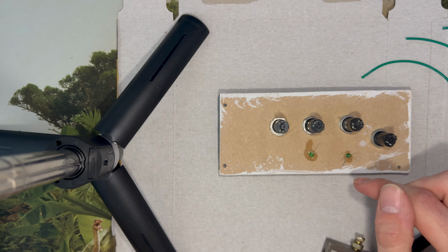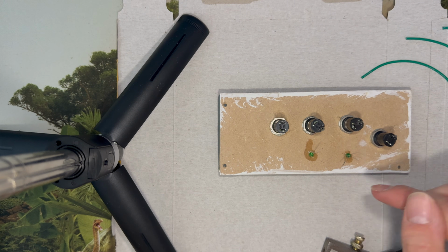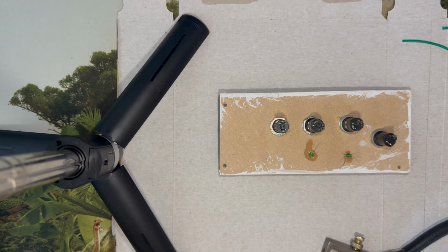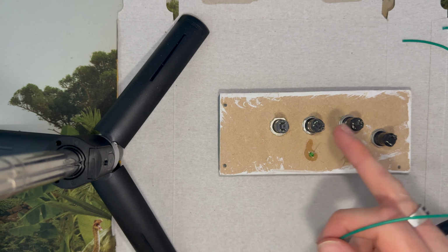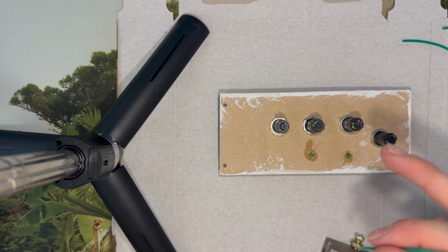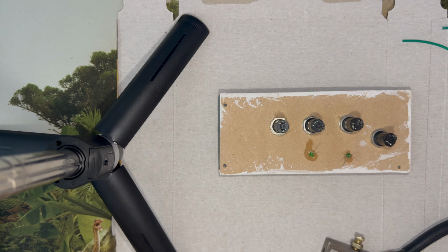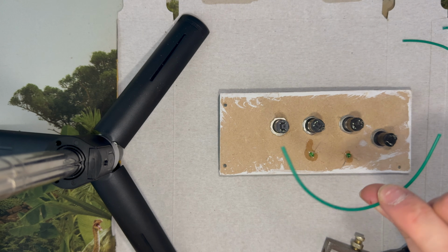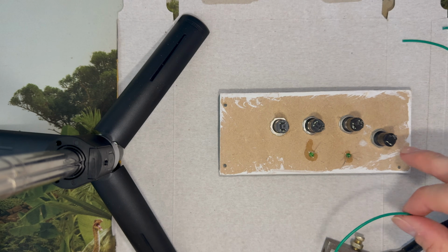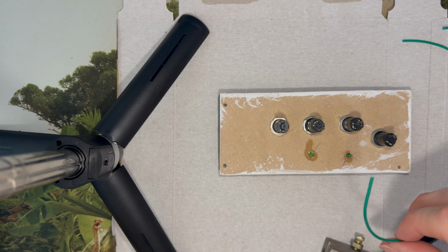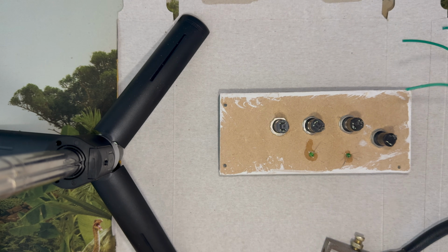So because of the board I'm going to be using, which we'll get into later in this video, I'm going to use a common ground, which means I'm going to link all the ground pins on all of these components together, and then just have one wire coming off all of them into the board. So we're going to do that now. So I've got 6 roughly equal pieces of wire that I've just cut. I'm going to trim the ends and connect them to the components before soldering them all together.